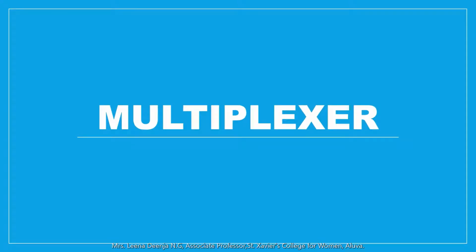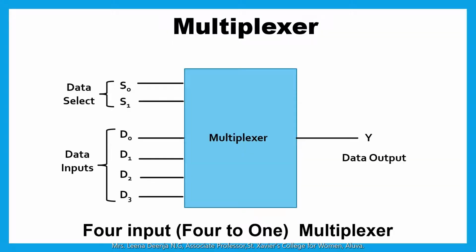Hi everyone. Through this class, we are going to study the definition of multiplexer, and the construction and working of 4 to 1 and 8 to 1 multiplexers. The multiplexer is a logic circuit that has several input data lines and a single output line. It consists of data select inputs that permit the selection of input digital data and route this data to a single output.